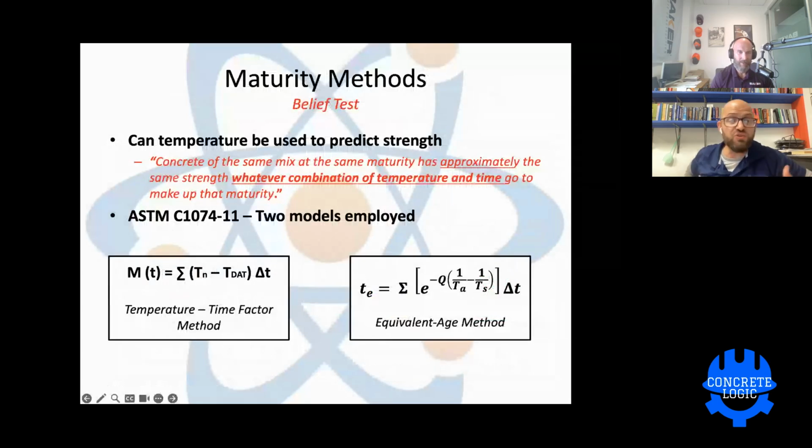And if you have a 0 there instead of a negative 7.2, well, what's the difference between a negative 7.2 and a 0? A negative 7.2 means that it can be negative 7 degrees Celsius out, which I don't know the conversion, but it's way colder than 0. At negative 7 degrees Celsius, my concrete can still set up. A type 1 at a 0.47 with no admixtures will have a problem setting up at negative 7 degrees Celsius. Is that a fair assumption?